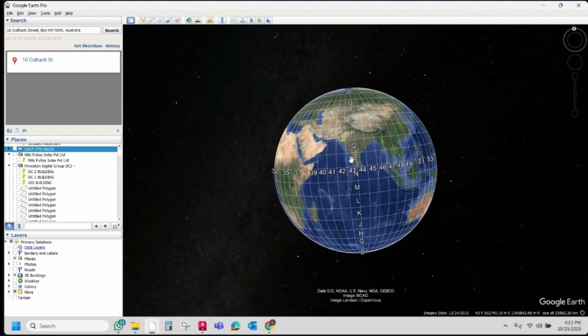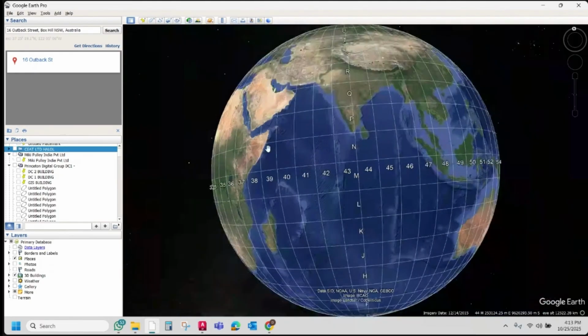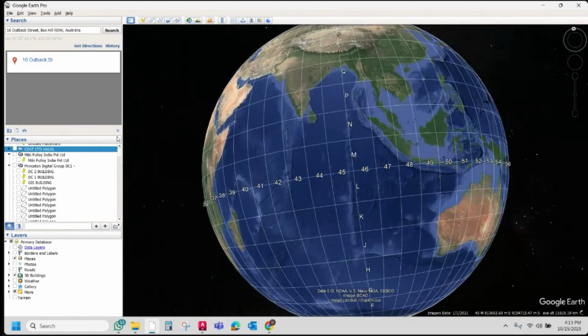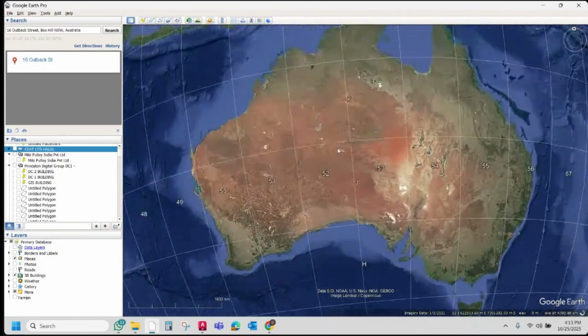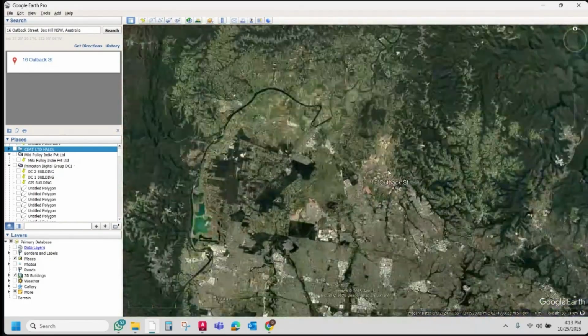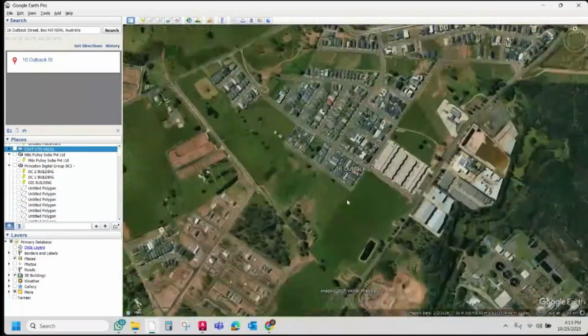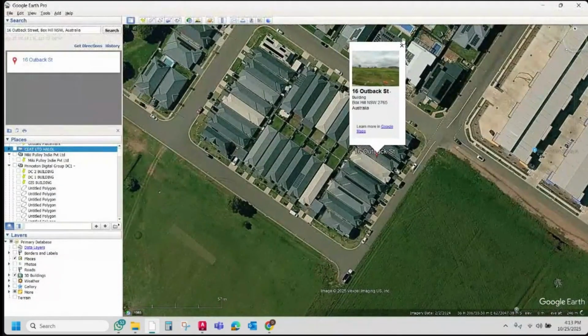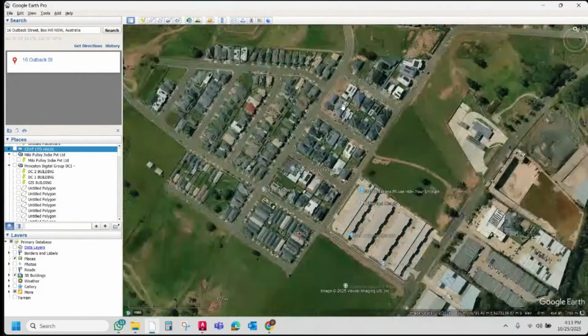So when we install above this line, it will be totally south facing, and below this line, it is totally north facing. So whenever we put panels here, we need to keep in mind that we install the north side first and then the south side.